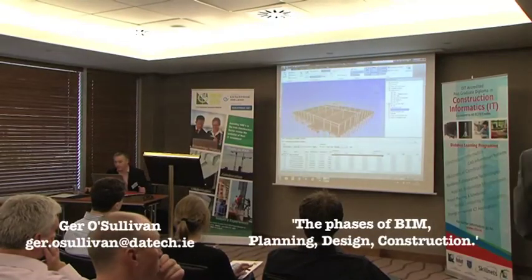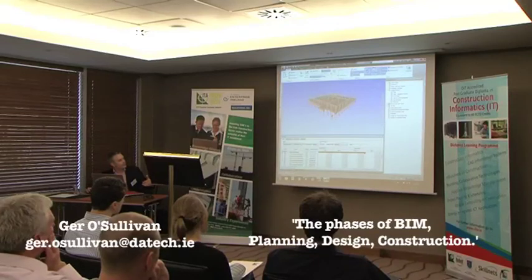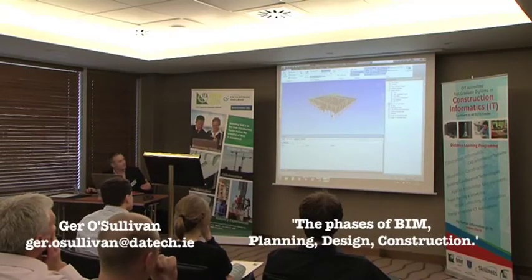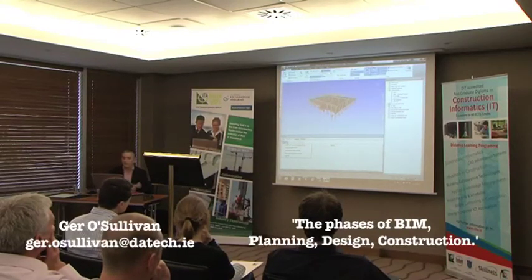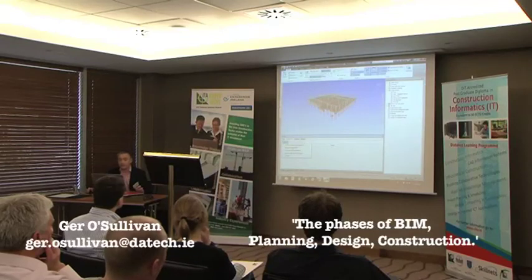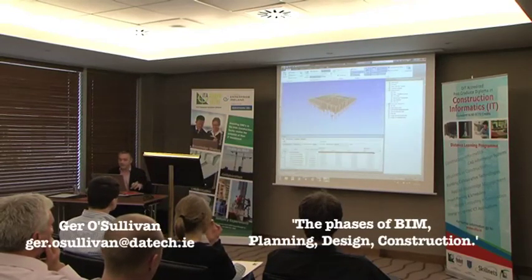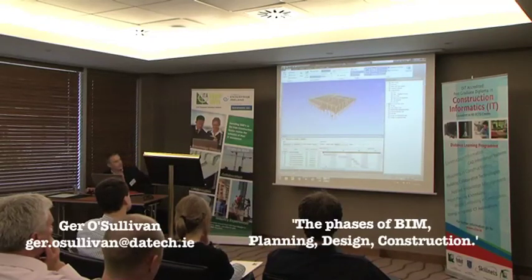We can go to our Timeliner, and I'm just going to quickly look at this, in that the Timeliner allows me to link in, I'll just very quickly show you, things like Microsoft Project files, Primavera, any CSV file, so Asta Powerproject will give you out a file. So we can bring that information in. It has all the tasks, it has the information on the time side of things. We can look at it here in a Gantt format, which is the nearest thing you'd see to that. And then we can create tasks within Navis.